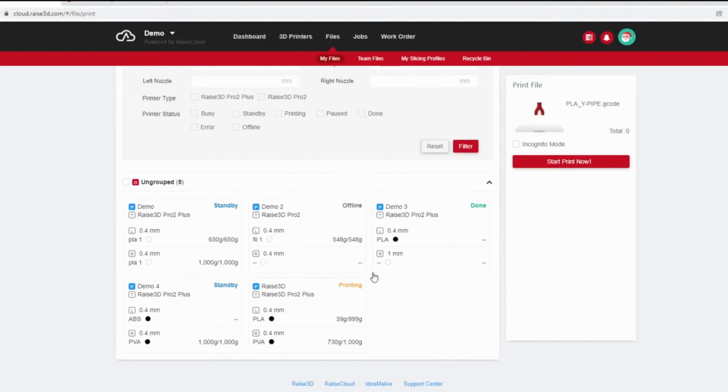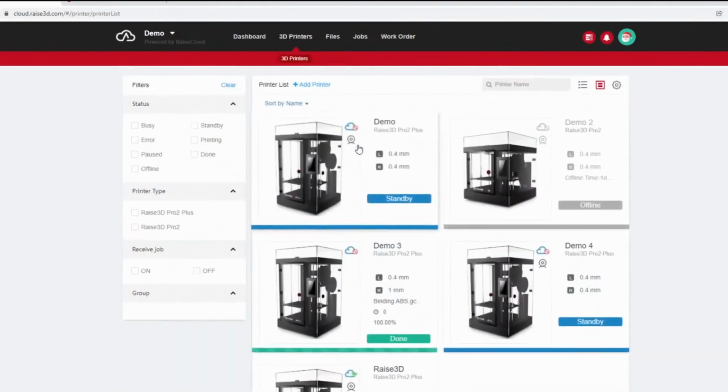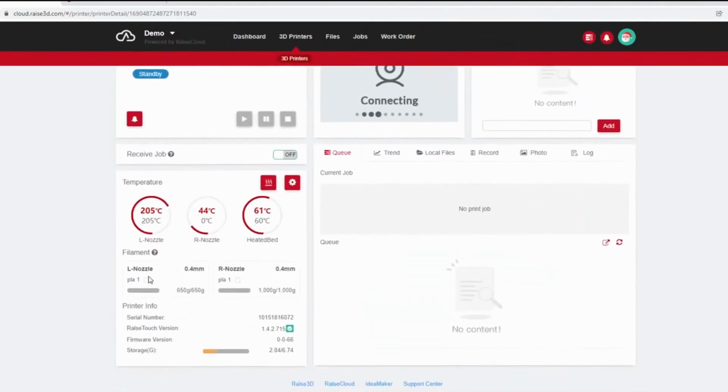if I wanted to have a setup for PLA and ABS parts, it is possible to tell the machines what they are loaded with. That is told on the touchscreen itself. It runs off of the filament profiles in there. So when you are loading in the different type of material, you just make sure that that's accurate and let that know what profile it's running, and then it'll show up to change here.